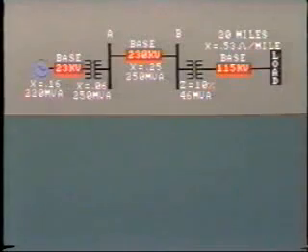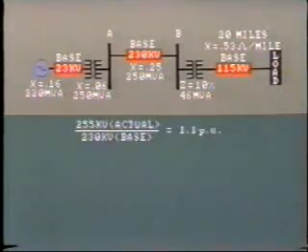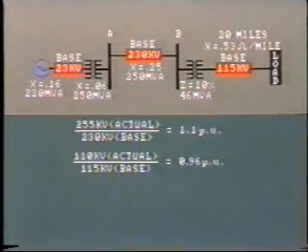Clearly, we will have several different voltage bases on most power systems. For example, an actual voltage of 255 kV divided by 230 kV base voltage gives us 1.1 per unit. On the other hand, a voltage of 110 kV on a 115 kV base gives a per unit value of 0.96 per unit.